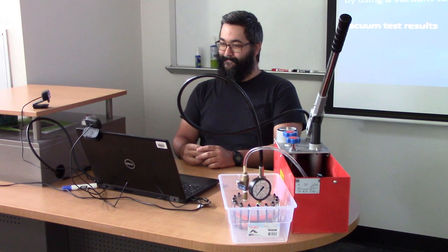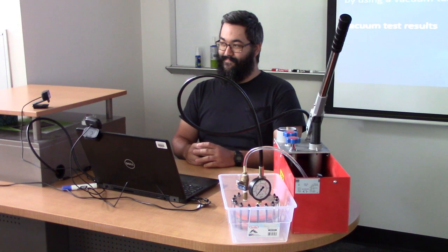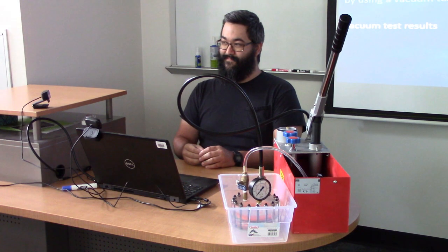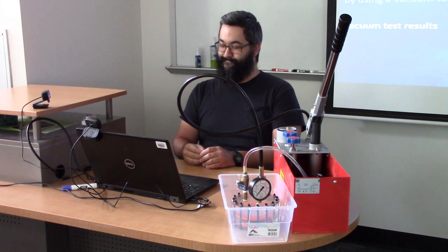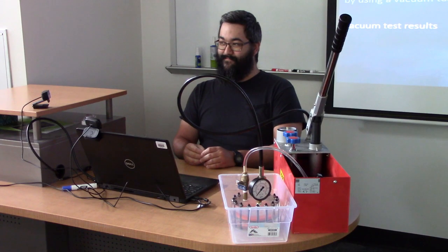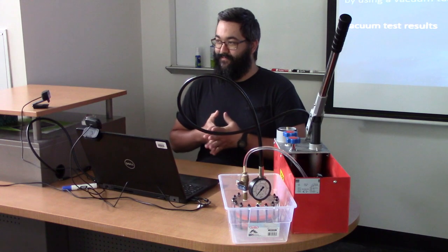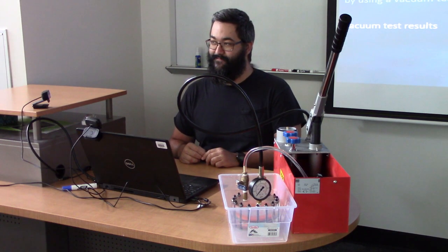So I have 2 more questions. One, now that we're on this slide, you said the extrusion multiplier actually made a huge difference, that the vacuum hold drastically increased from 2 minutes to 3+ hours, right? So does that parameter control the speed of the layering, that it goes slower and more material is laid down, or is it literally the amount of material coming out of the nozzle at a constant speed?